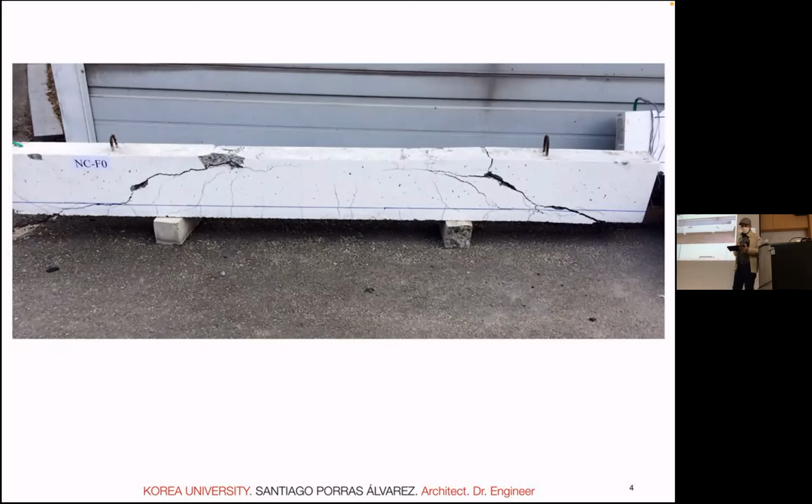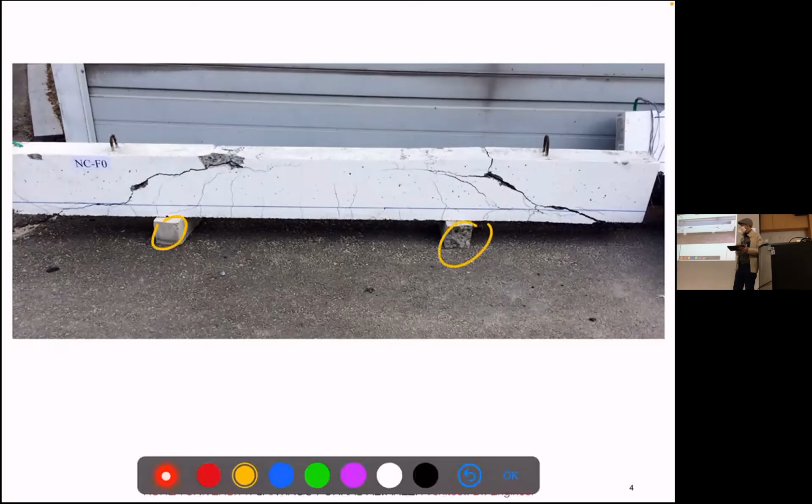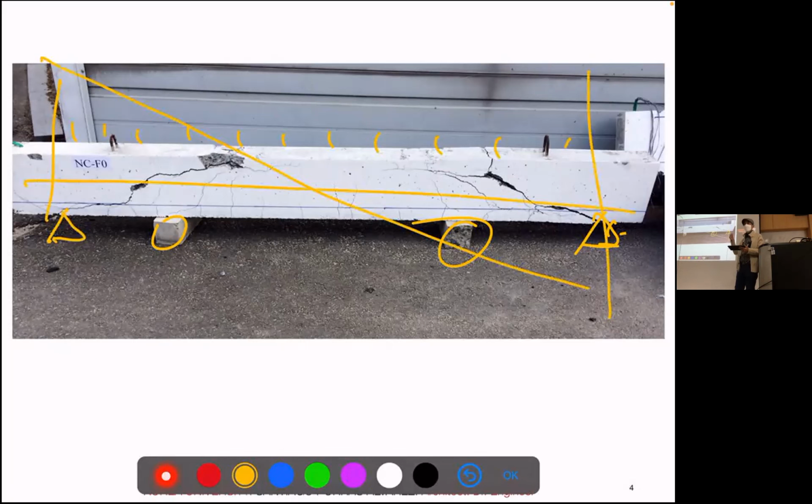This is just as it is now, but probably the beam was supported on two sides, right? And with a continuous load. In that case, the graph of the shear is like this. So the strongest stress is near the support. This is why the crack happens there, and how you draw it.